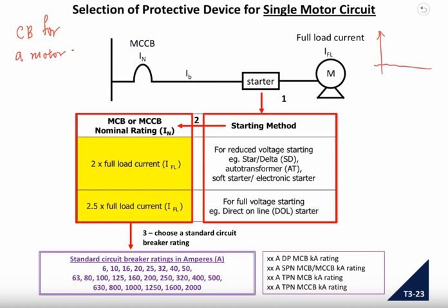When we try to start it, it will have a very high current, which looks like this. Okay, this is current, this is time. And so we have a device which we call the motor starter to bring down the starting current. Okay, two function. One, to lower the starting current,